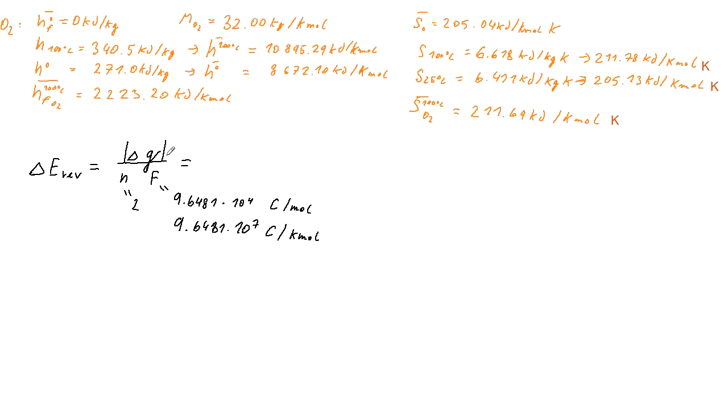Perhaps we can write it like this. So it's 1.685 volts. Now the real voltage of fuel cells is determined experimentally for each case, based on how well you manufacture it, what catalysts you use on the electrodes, etc. The typical values are between, let's say, 0.5 to 0.9 volts. So we will assume that the value will be, in our case, 0.8 volts.